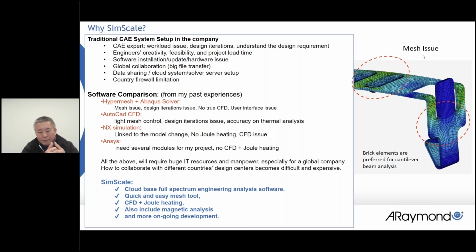Usually in the connector world, we like to use cantilever beam analysis. We'll prefer using a brick element. So sometimes with this complicated geometry in the previous software we were using, it might take half a day or one day to meet all of the good mesh quality. That's why a lot of companies are outsourcing their simulation work to a different location.